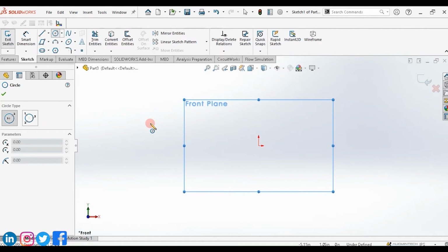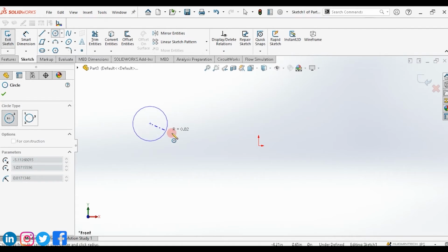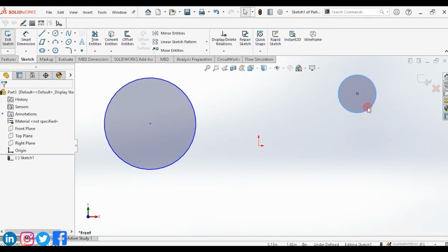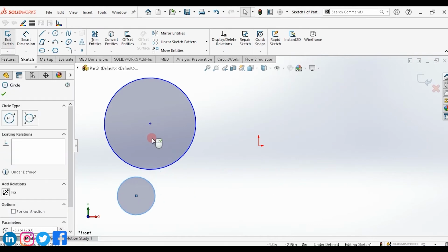We have to draw the central circle or normal circle at any point. The circle will be created around the center of that circle, and we can increase and decrease the radius of the circle this way. After releasing the click button, the circle will be drawn. So in this way we can draw any central circle of any size. These circles are undefined, so we can move these circles from one point to another point of the plane, at any point of the plane.